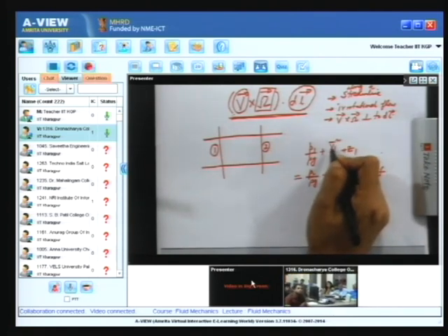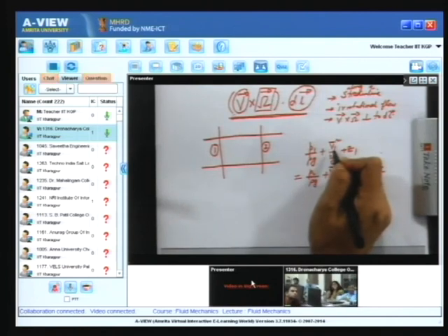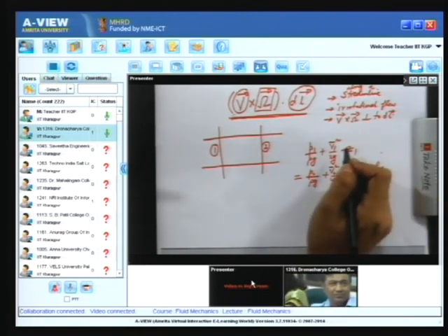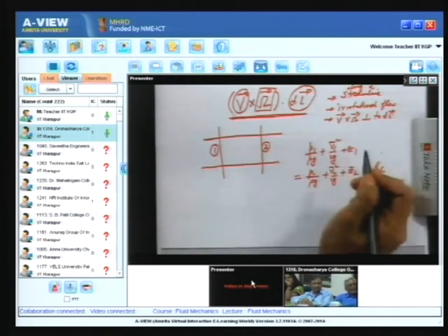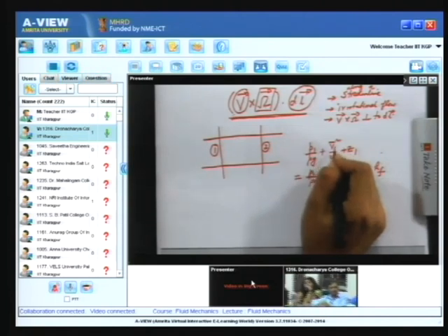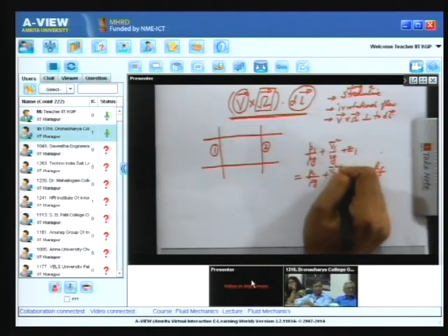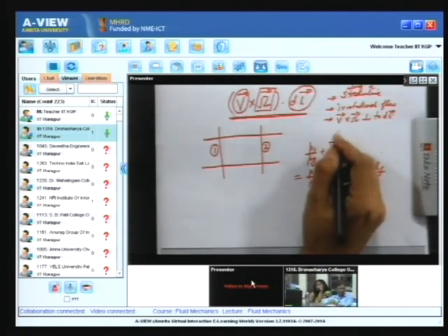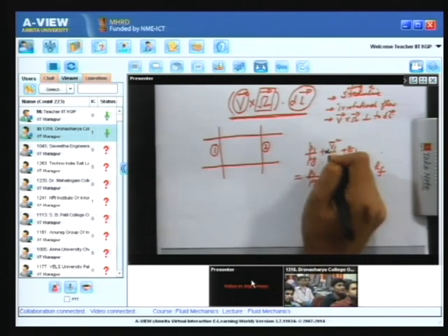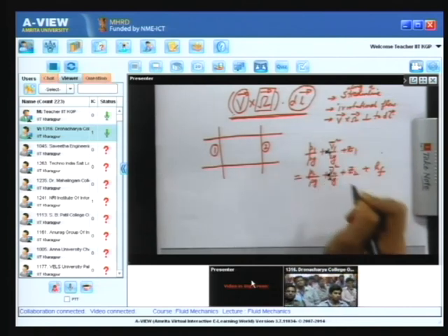The average velocity will represent the kinetic energy of the section when the velocity profile is uniform, which is maybe very closely true for turbulent flow, which we will discuss later on. But for laminar flow there is a significant difference between velocities between points, because the velocity profile itself is parabolic. So to take care of the velocity profile you multiply with correction factors alpha 1 and alpha 2 which are called kinetic energy correction factors.